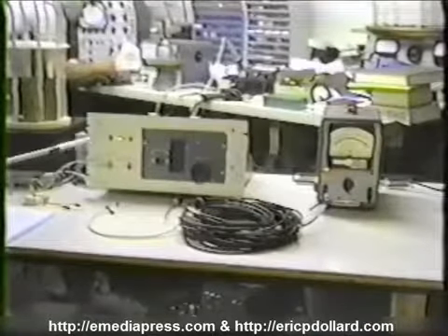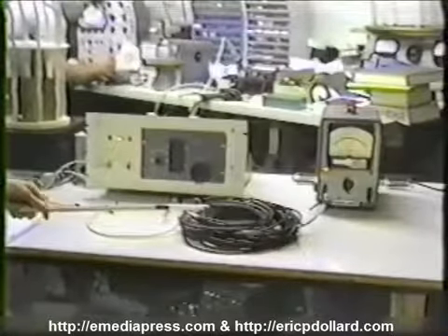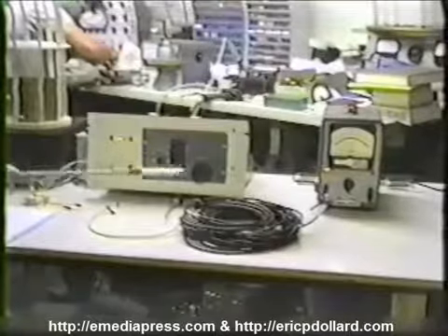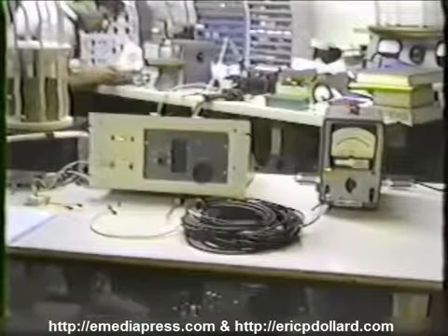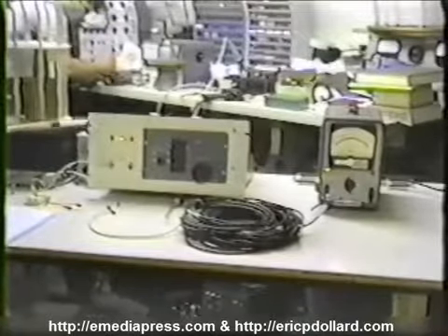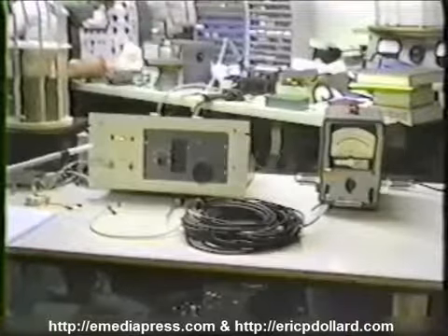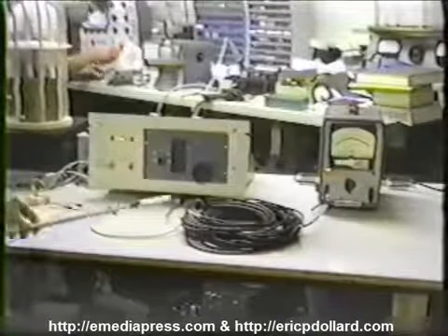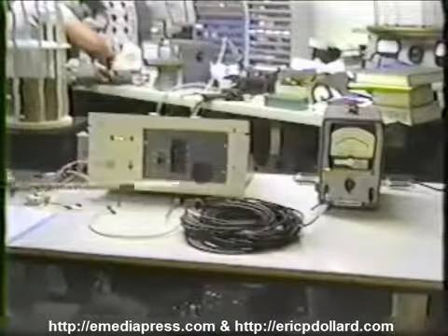When the impulses of the oscillator frequency are such that they match the time of propagation delay produced by the propagation of electricity down the cable, when this inverted impulse comes back from reflection, the oscillator has gone through 1/2 of a cycle, and it also is producing an inverted impulse. So these two inverted impulses add, and a double impulse goes back down the cable, turns right side up when it gets reflected, comes back to the oscillator.